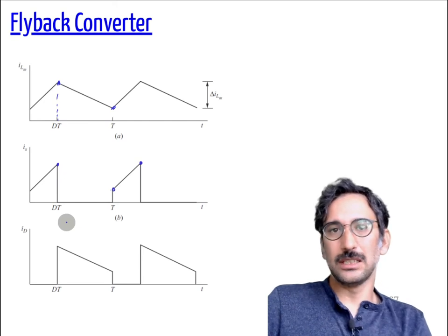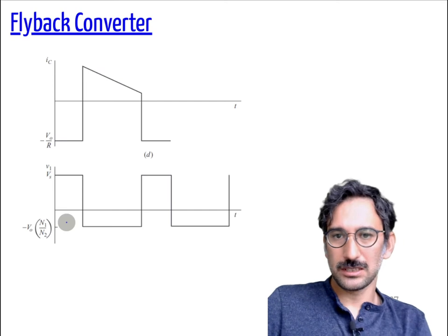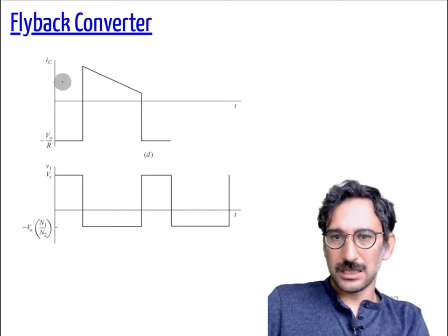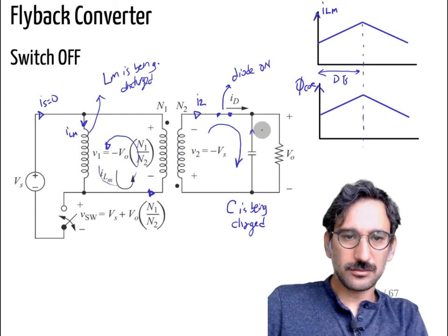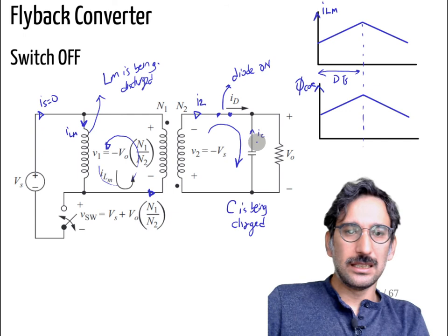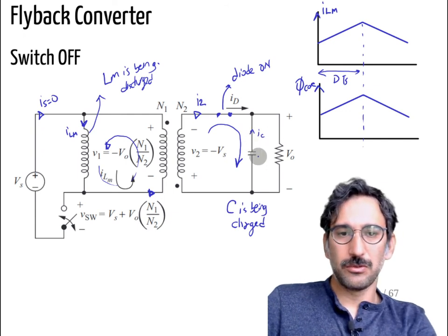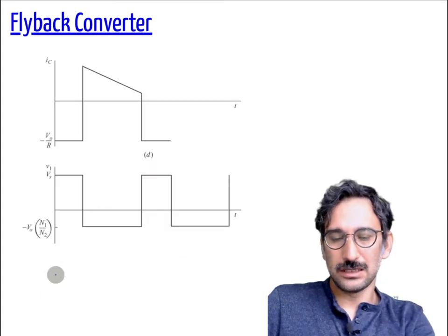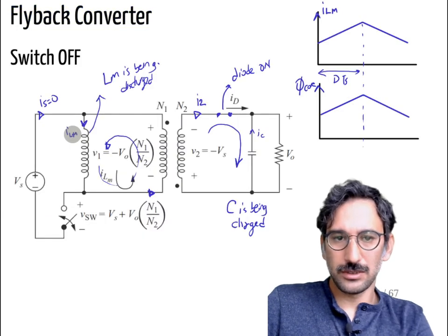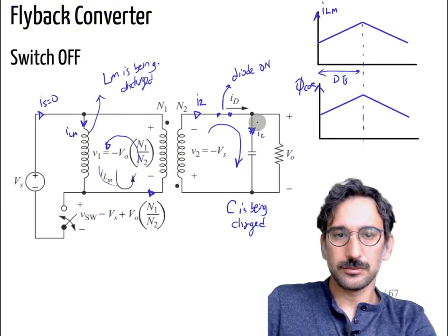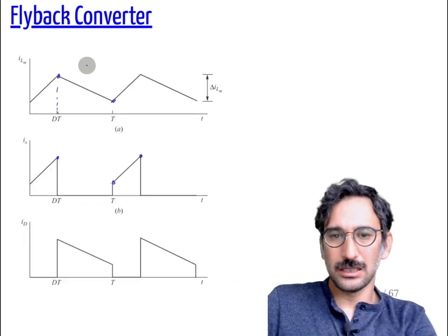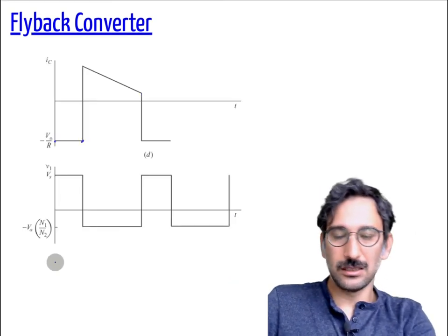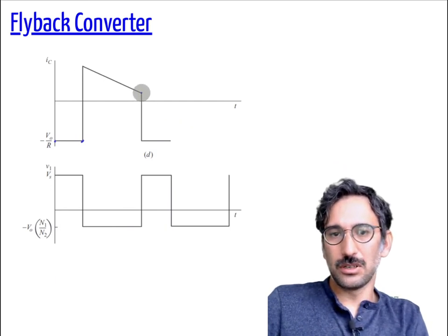Don't forget the N1 and N2 terms. Anyway, we will derive those things. And if you look at the capacitor current, again I assume C is quite large. Which way it's positive, I don't know. Let's say the positive is in that direction. Let's define the capacitor current like that. So whenever the diode is off, your capacitor is being discharged with some constant current, and then the diode current minus the load current is charging your capacitor.